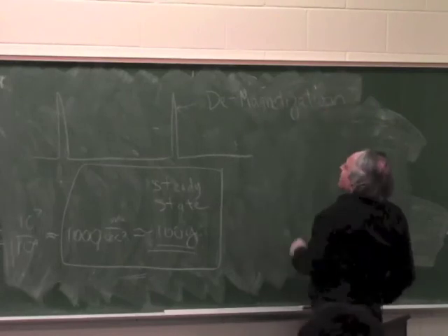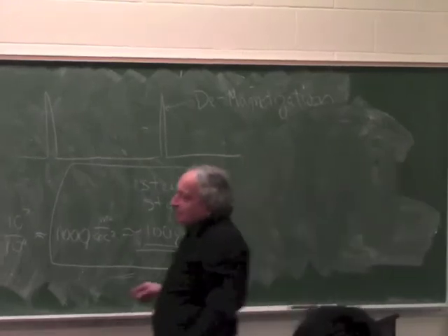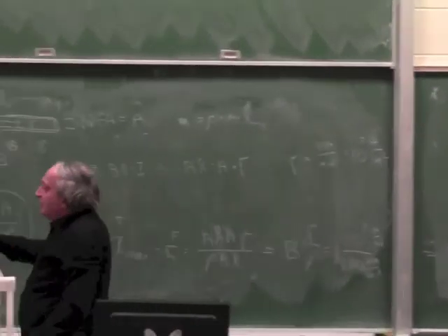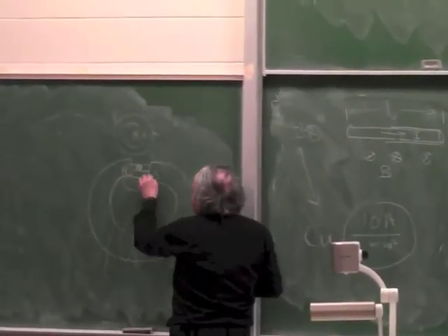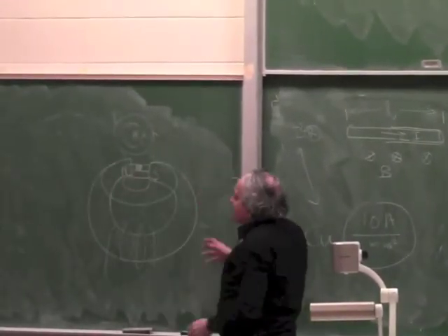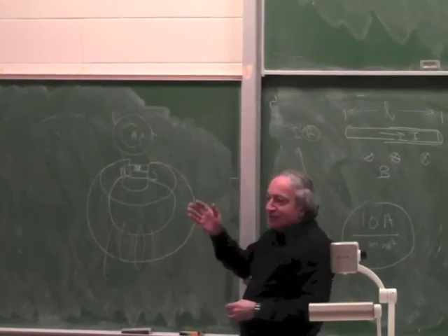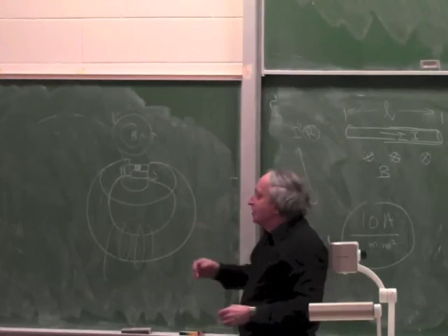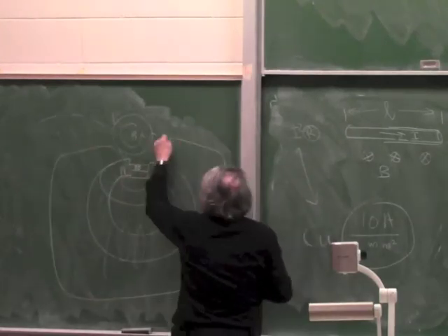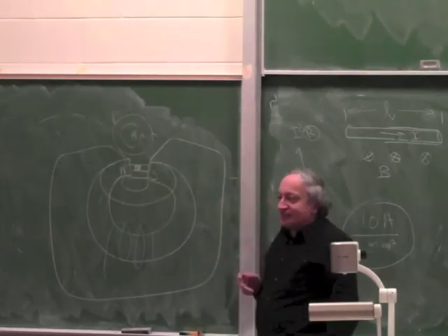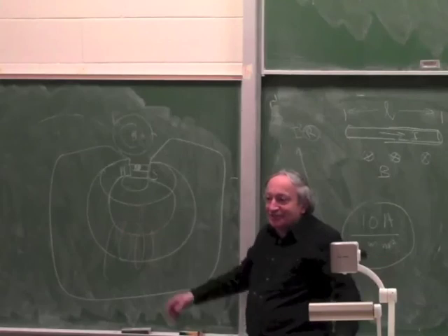And of course here the limit is not a hard number, because you can make this magnet bigger and bigger. So if you want an actuator which works steady state, you can make this magnet quite small, because nothing will demagnetize it. But if you want an actuator which has to work at very fast pulses, at huge acceleration, you can make this magnet huge. So it will be very difficult to demagnetize it. Because this magnet doesn't have to move, so you can make it as big as you want.